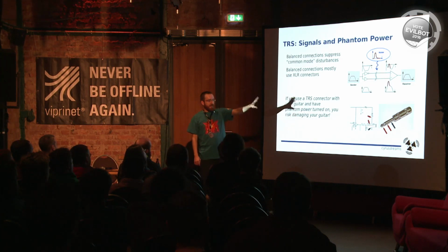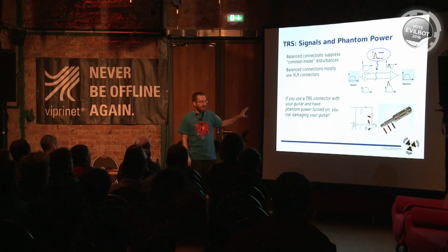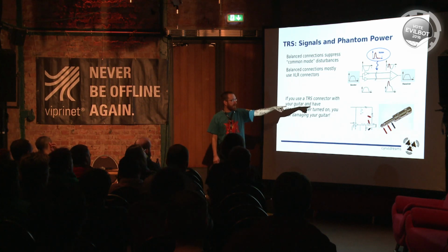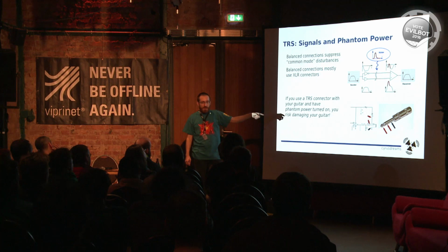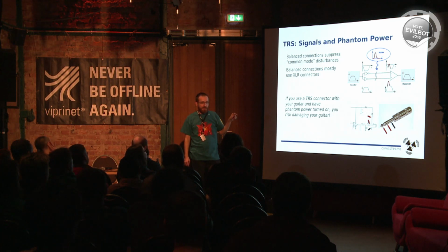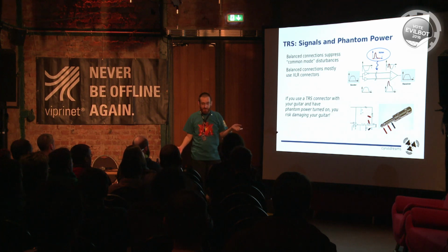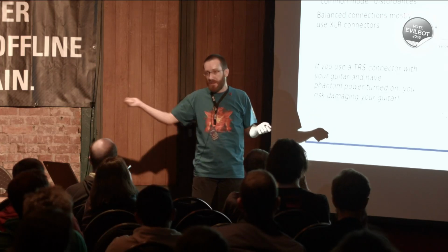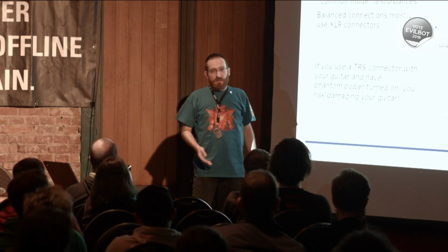But having this and at the same time the old style for the guitar might be a problem if you have complex installations and you don't know what you're doing. If you use a TRS connector, tip ring sleeve, and you have the phantom power on, and you plug that one into a guitar, you risk damaging the active amp that's in there. And it really happened to me 2 times. We had a setup where we just didn't have the proper adapters. You normally use what's called a DI box. If anyone comes to you with an electric guitar and wants to be plugged into your mixer, normally you put a DI box in between